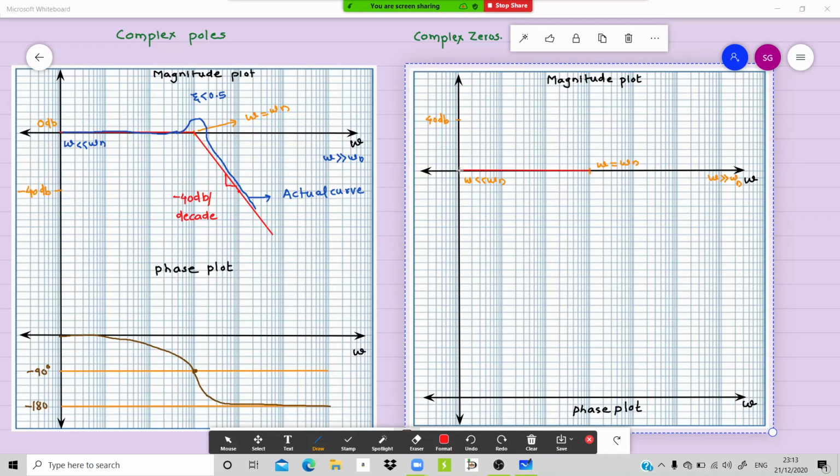After that it should be a slope of plus 40 dB. So this is plus 40 over here for the next decade. And a line passing through it we are supposed to draw. So I'm drawing. Alright. And I'll write over here the slope is 40 dB per decade. Plus 40. Correct. And the exact curve if you want to draw.